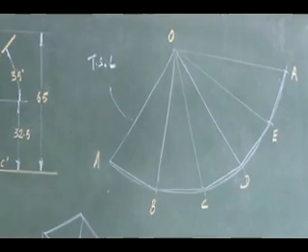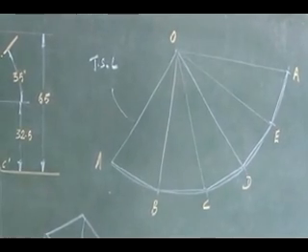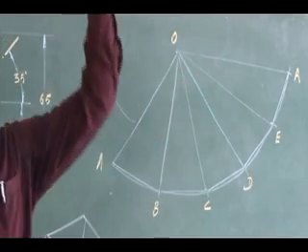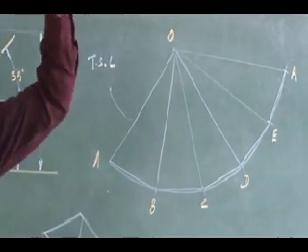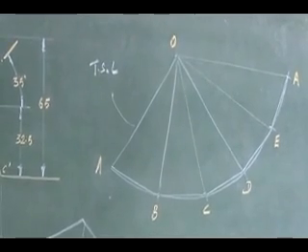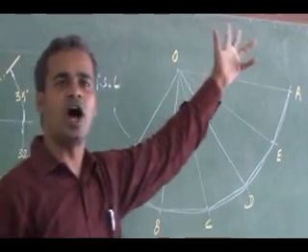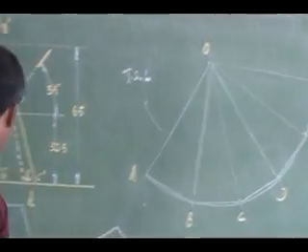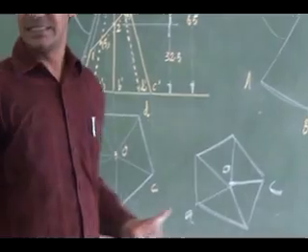That is going to be my development of a pentagonal pyramid. For development of a pentagonal pyramid, you need a true slant length. In your projection, you have to get it. Once you have got it, you can draw an arc. You can mark any location, draw an arc, then you can measure your base side length.